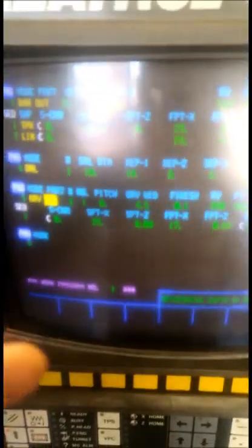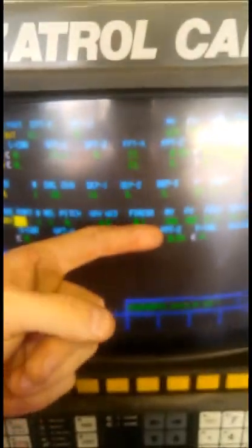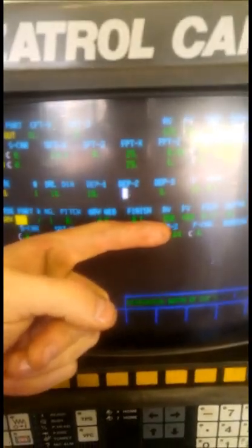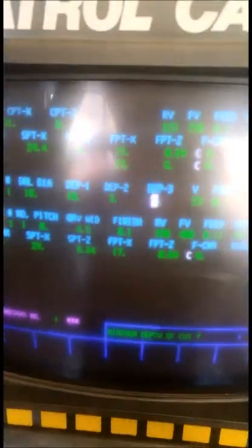So first cut goes in 10mm, then it backs out and comes back in, and then it will go in 7mm, because that's your 10 minus 3, and then it'll come back out, and then it'll go in 4mm, because that's minus another 3, back out, and it'll keep doing that until it gets to this depth 3, which is your minimum depth of cut. So that's the minimum amount that it'll peck each time.